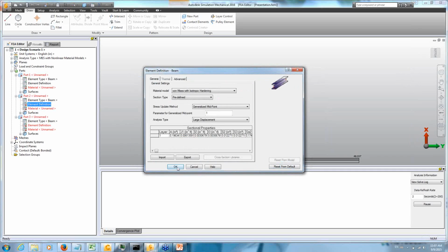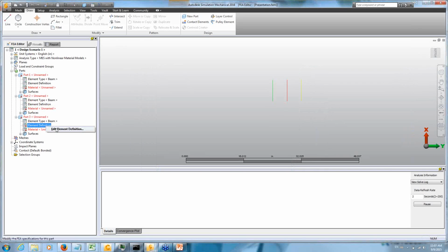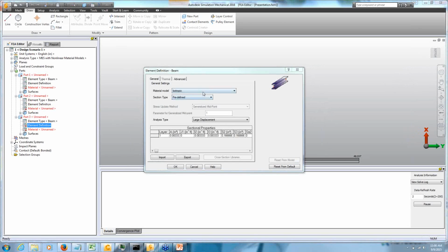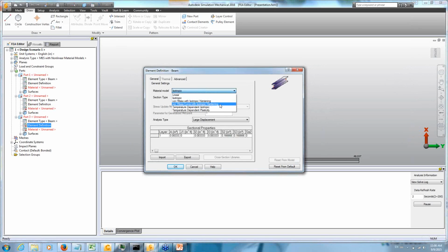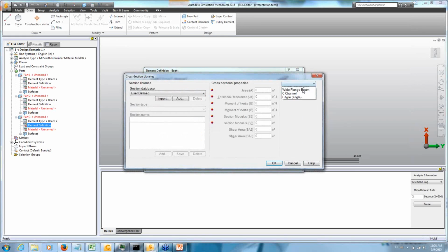And so, Marwan, when we set this up, we're actually going to look at the same boundary constraints, the same loading, and then we're going to be able to view how this is responding with the different material models. Exactly, yes. And this is coming in just a minute here. So the last one is going to be von Mises curve with isotropic hardening. So it's going to have a curve behavior beyond yield.